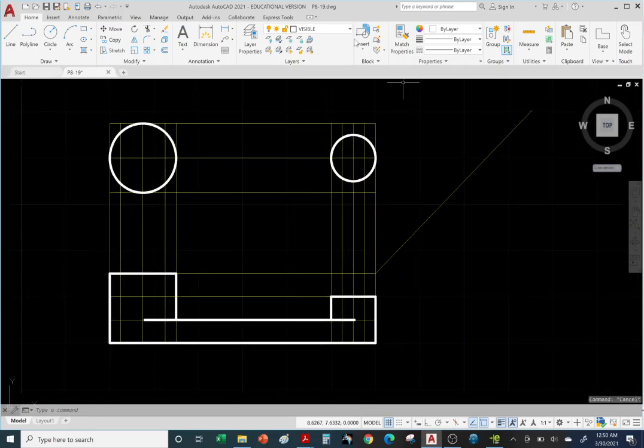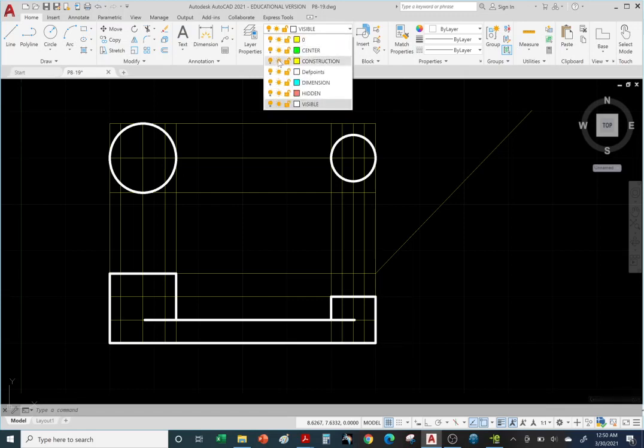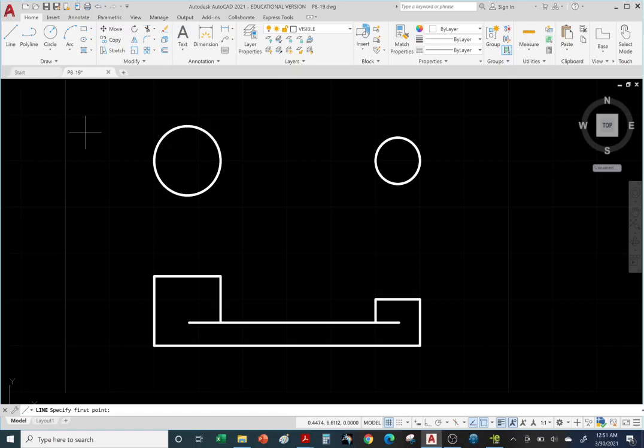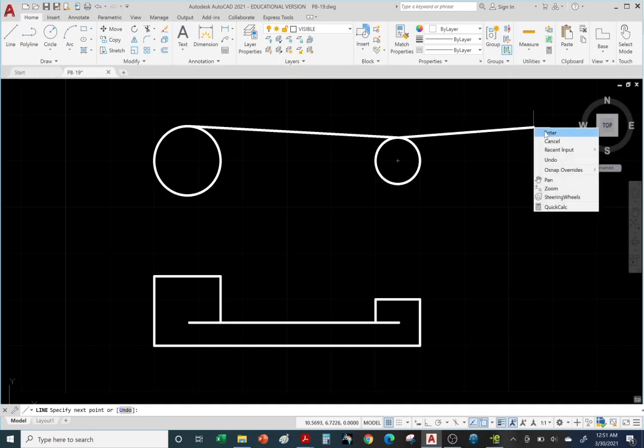All right, so now let's temporarily turn off our construction lines. Now we're going to connect the two circles using the line command and TAN, for tangency. Once you click on the line command, type in TAN, enter. Let's do the top portion first. Now we can see the green lantern ring, right? Click. Okay, there it is. You can see it's tangent to the top portion, and then we'll type in TAN again a second time, enter. As long as you hover anywhere on the top half, it'll automatically make a tangent. Click. There it is. See how it made a tangent, and right click enter.